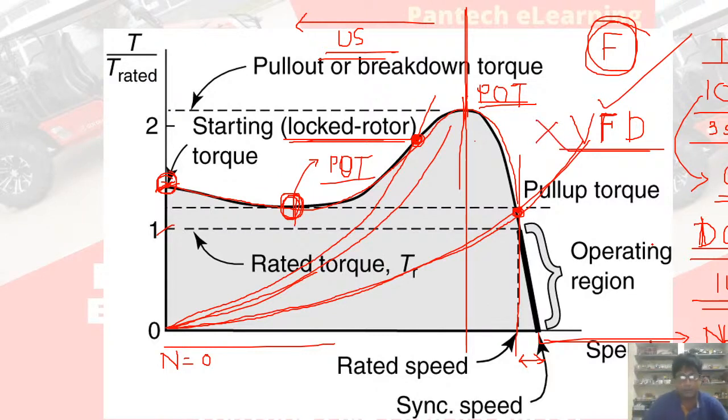Why? So when you will be working in industry, you are taking some project for some chemical or refinery or somewhere. So the first thing they will ask you is to select the motor. They will give you this curve. They will tell you have to overcome this system resistance, and based on that you select your motor and make the data sheet and give it to us for approval.